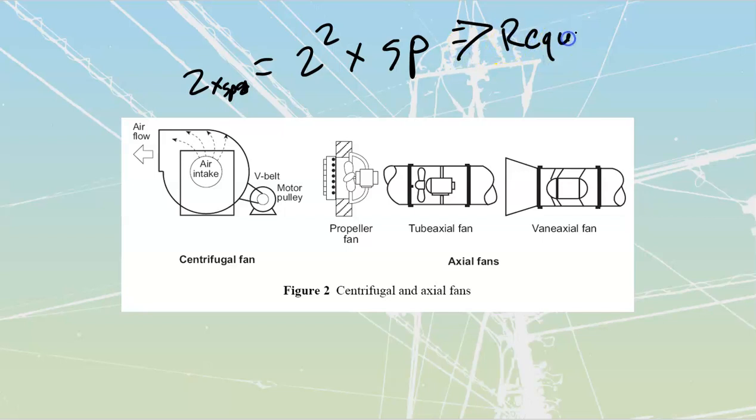It doesn't create 8x, oops, I'll do 2 cubed. It requires 2 cubed, which is your value of 8, the horsepower. It takes a lot more work to square up your static pressure and double your airspeed out of these things. It's a misunderstood thing. It doesn't seem like it takes a lot to move air, but when you're moving air inside of confined spaces like ducts, there is absolutely a massive demand on your horsepower.